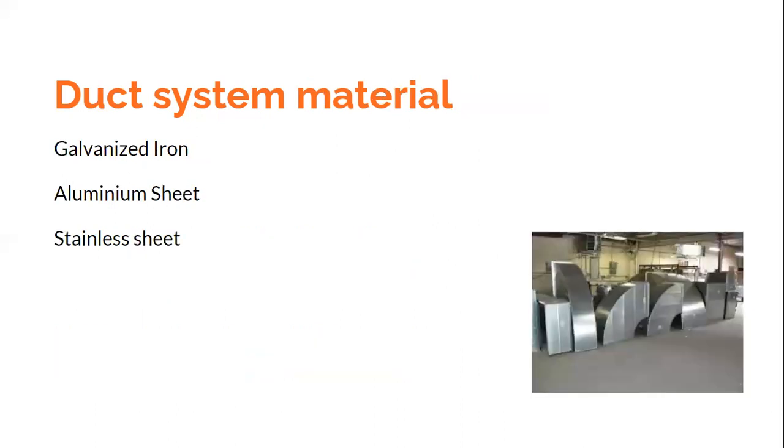As I said, we should be worried about the classification because it impacts the air distribution system. The duct has to be sized. Ultimately, we need to design the duct so that it is accommodated within the available space. Like any other fluid passing through a pipe, for example, water passing through a pipe, similarly the air is passing through a duct, and as I said, this duct would suffer a pressure drop because of friction.